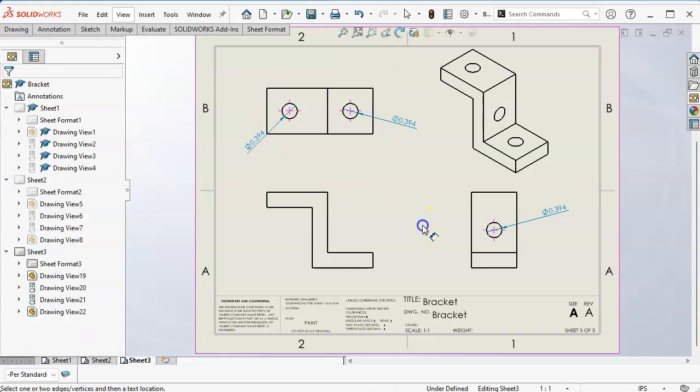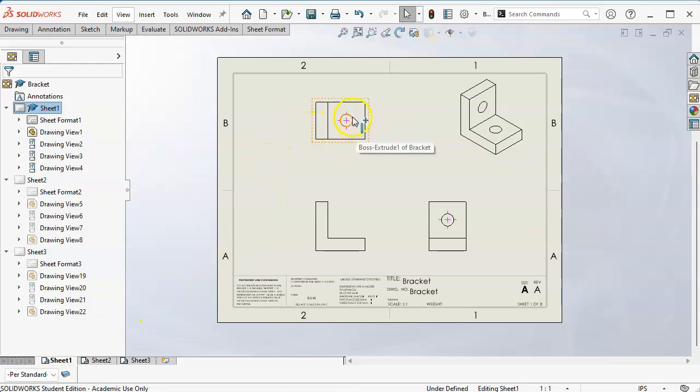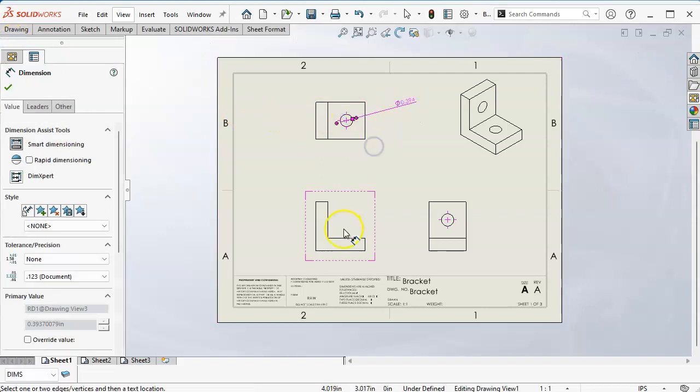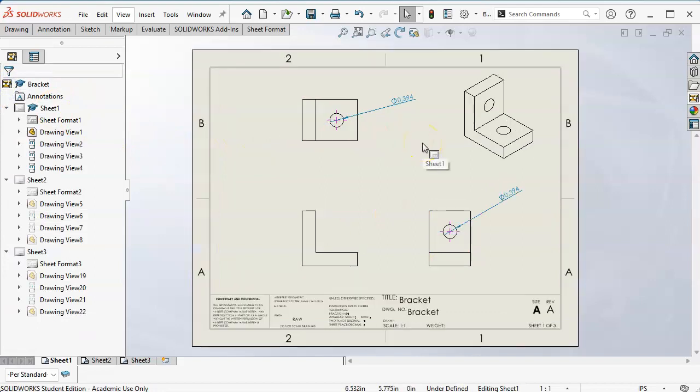All right, and then this is my iterations of drawings. Typically, if I'm doing multi-sheet, I will go through and add the parts and think about the sequence. And then the next one is to go through and do basic dimensions and start to think about tolerances. And then the next pass is a tolerance pass, and then the next pass is to go to GD&T, or geometric dimensioning and tolerancing. So as it goes through each of these steps, we're refining, we're getting a little closer, we're getting something that's a little bit more manufacturable.